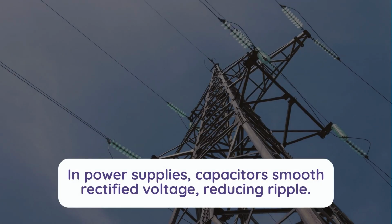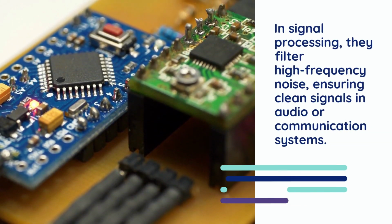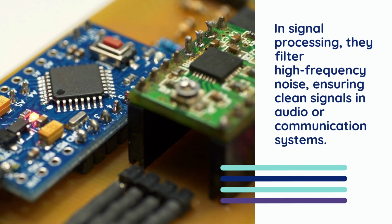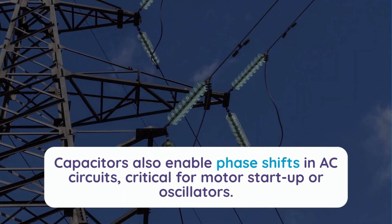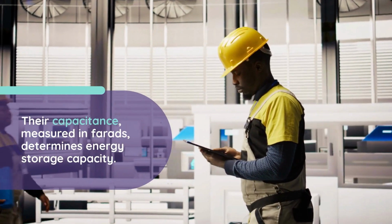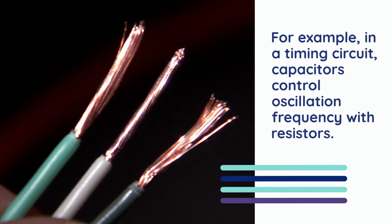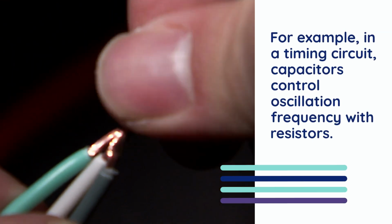In power supplies, capacitors smooth rectified voltage, reducing ripple. In signal processing, they filter high-frequency noise, ensuring clean signals in audio or communication systems. Capacitors also enable phase shifts in AC circuits, critical for motor startup or oscillators. Their capacitance, measured in farads, determines energy storage capacity. For example, in a timing circuit, capacitors control oscillation frequency with resistors.